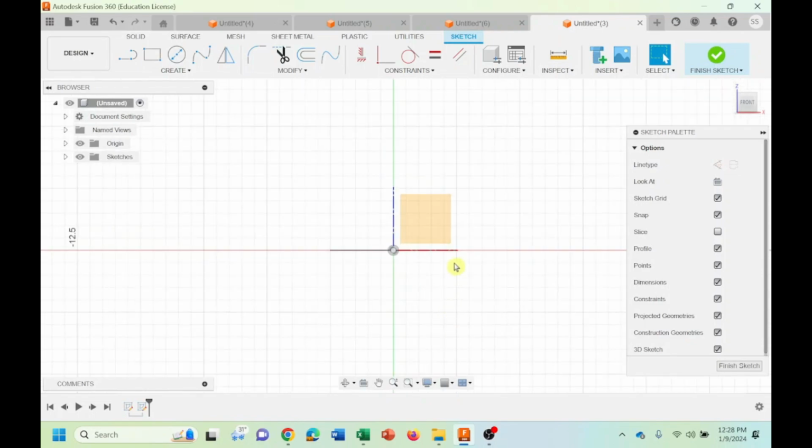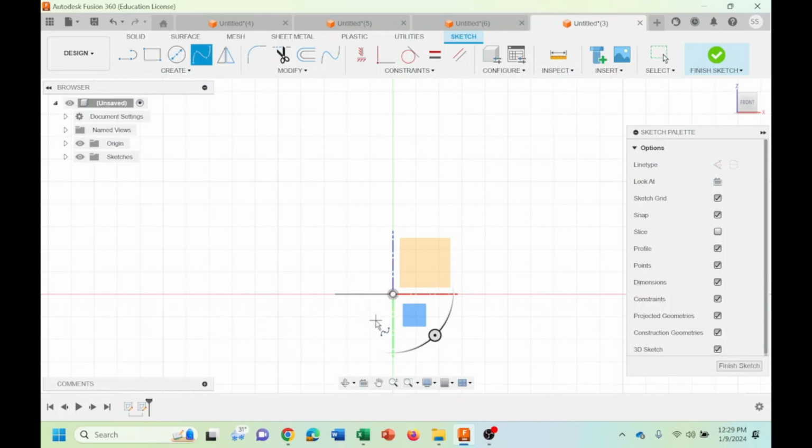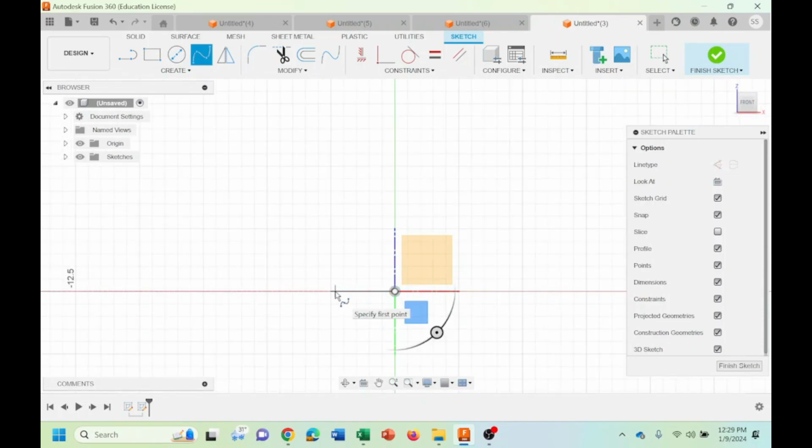For having that line, because you are going to sweep this surface, your spline should be big enough that the surface is able to sweep around it. Whenever you use this spline, we should be careful to give it enough space for the sweep that we are going to have. If you check my shape here, it is almost one square, so I'm going to double that to give enough space whenever I sweep it. Let's do this.